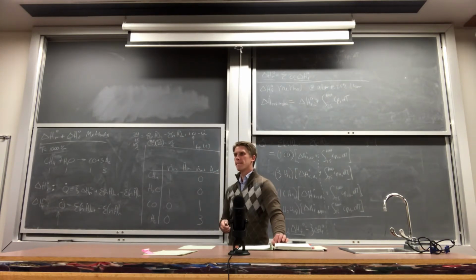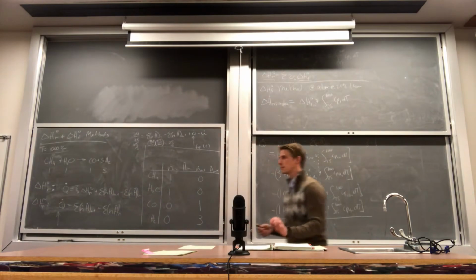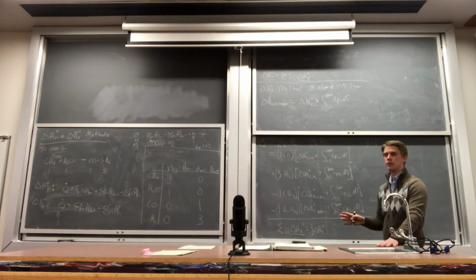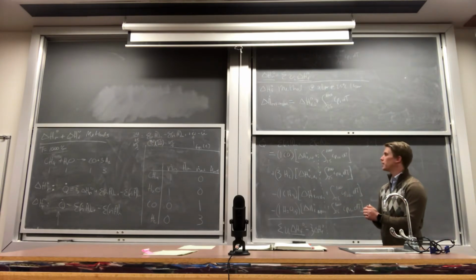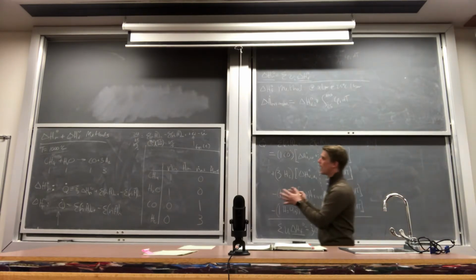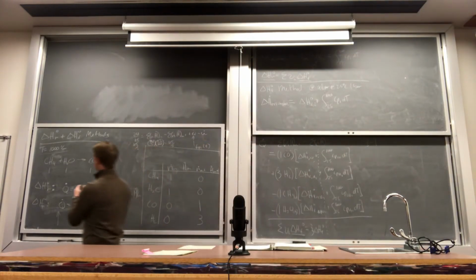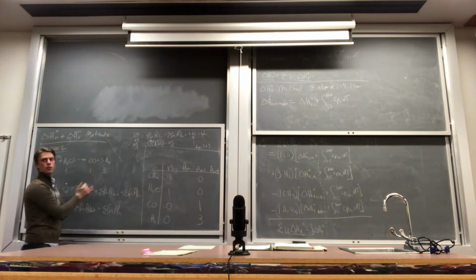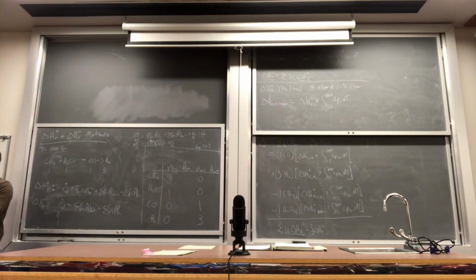I'm still a little confused. Mhm. So the ultimate equation you ended up with is the equation for the heat of reaction approach. They're the same equation. It all depends on how we want to organize our thoughts. In the heat of reaction approach, what we're thinking of is we're keeping track of the energy coming in from the methane and water and the energy coming out in the CO and hydrogen, and then the reaction is either releasing energy or consuming energy. That's sort of how we're thinking about it in the heat of reaction approach.